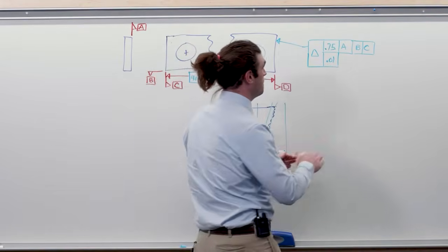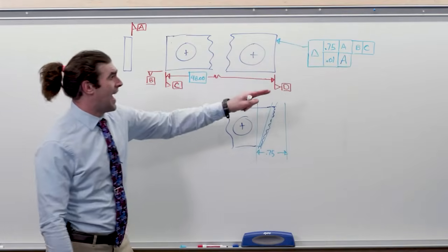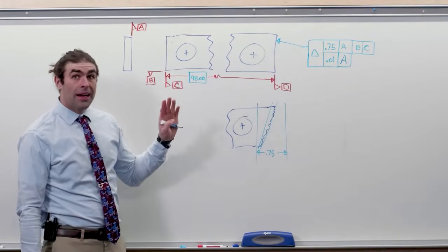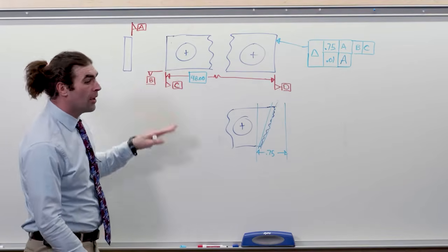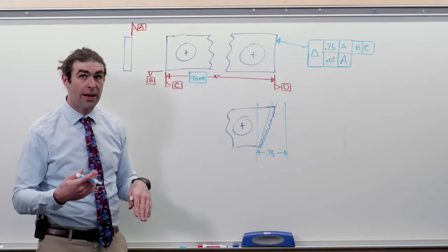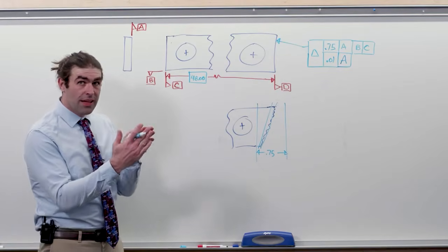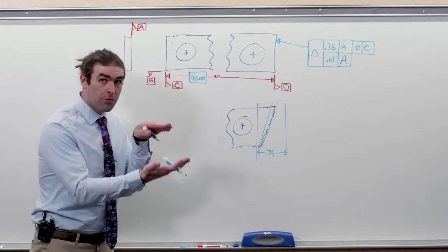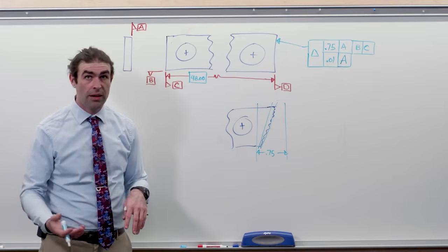So I'm going to do that. We're going to add datum A. Now it's difficult to see here because datum A is that large surface, but you could potentially, without referencing datum A in the second segment, even the thin portion of the part could be out by 3/4 of an inch, which isn't what we want.